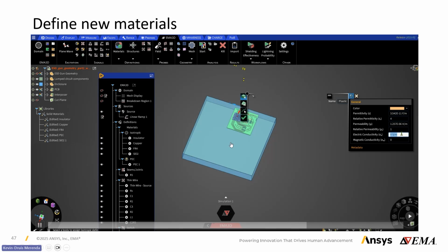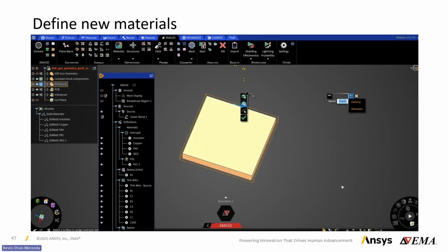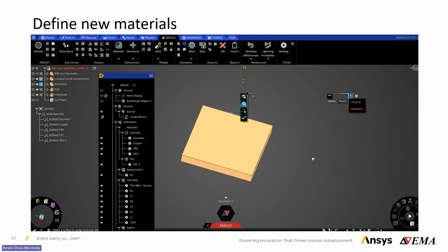So the electric conductivity of that enclosure is key. This is very applicable for any devices like earbuds, mouse, keyboards, cell phones with cases. You could think of cameras. I'm looking at everything on my desk right now that has a PCB inside a plastic enclosure. There's going to be a lot of risk of ESD and discharging to that device.